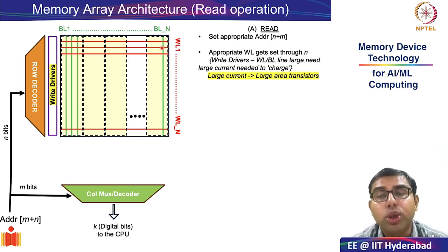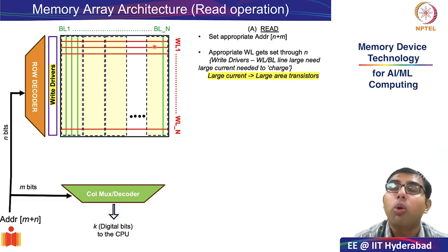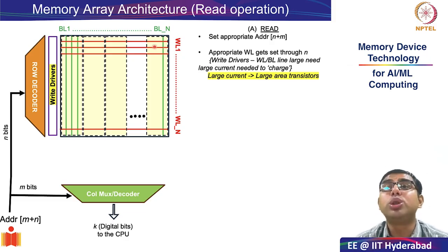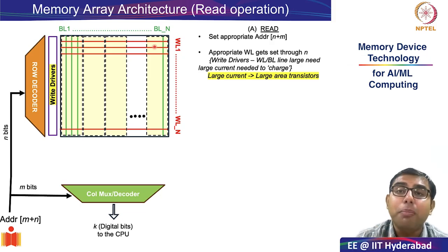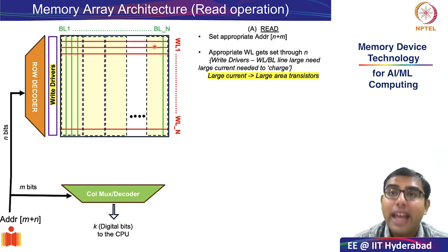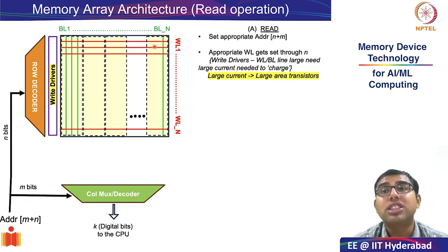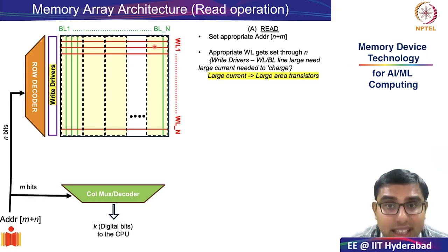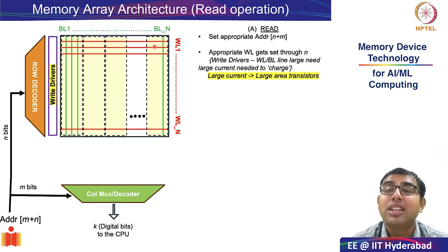So in addition to the resistive element of these word lines, you also have to consider that they have some capacitive component. Any real life wire will not just have resistance, but it will also have capacitance. And these capacitance effects start playing a very important role when you shrink the size of these interconnects and start operating at higher frequencies.